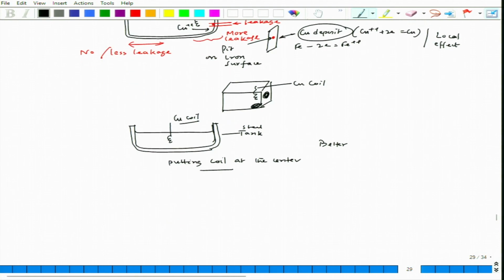If we increase the resistance of the electrolyte, for example, if we use salt water, deionized water and distilled water, we will see that the corrosion of the metal container will be less in case of deionized water, because its resistance will be the maximum of the 3 cases, and the salt water would give the maximum corrosion of that metallic container, because it will have the highest conductivity.